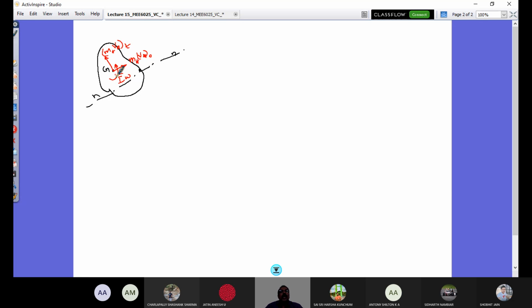If that is so, the momentum present in this is because it is general plane motion. So we assume it is 2D motion, and the rigid body would have its general plane motion with reference to the reference plane, which is the symmetry plane of the body. So at CG you have its linear momentum as well as angular momentum represented like this. This corresponds to body A or vehicle A just at the beginning of the impact.